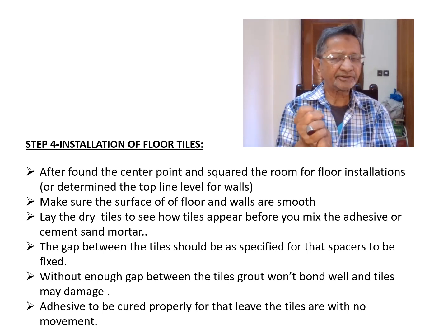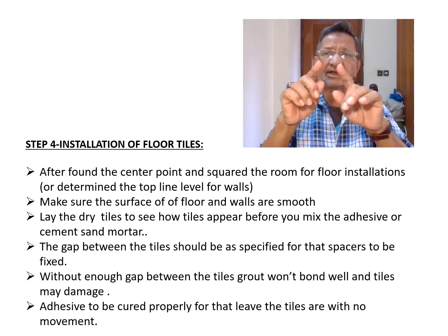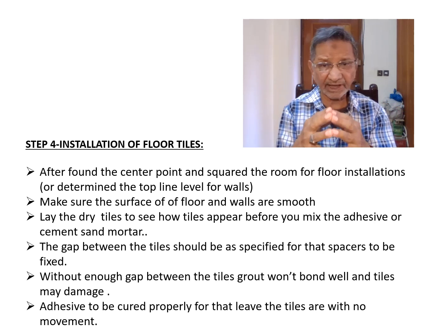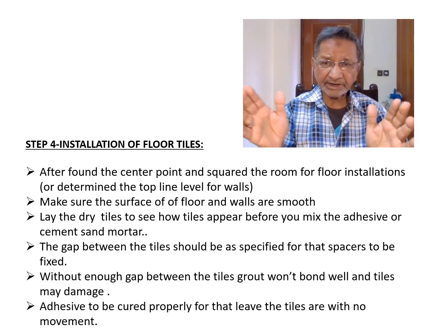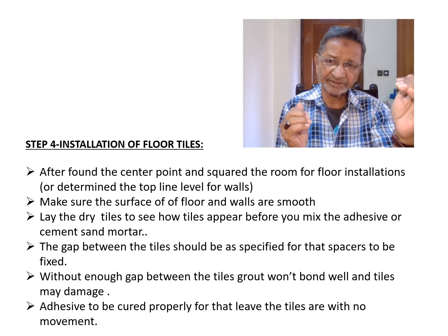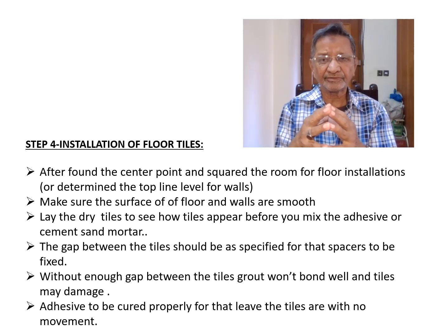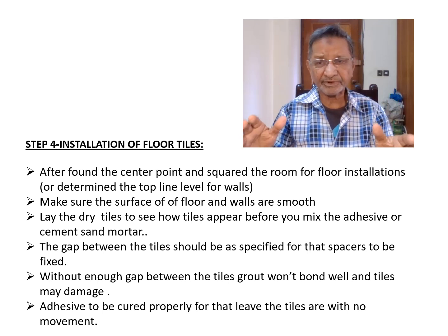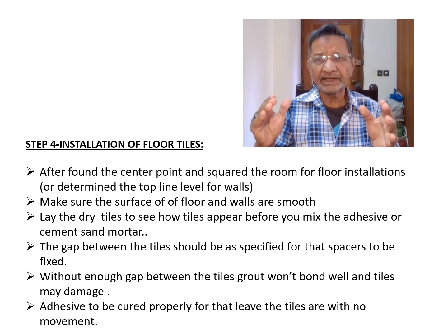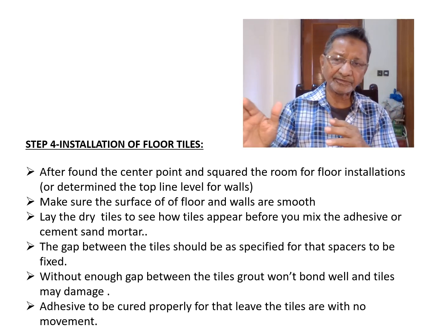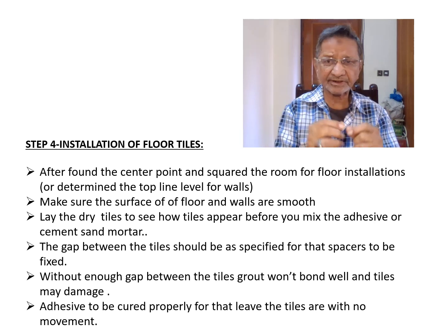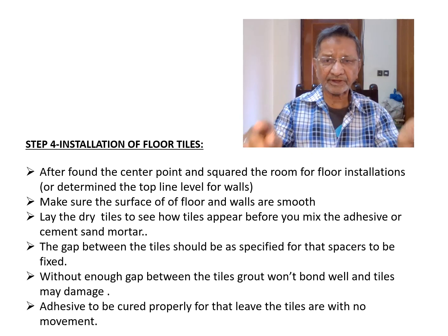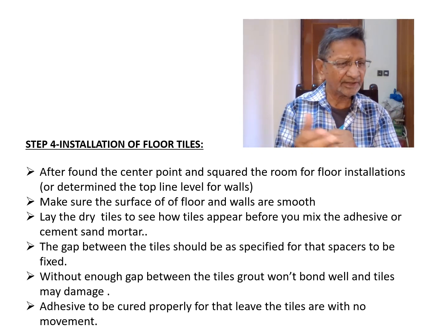The first step is that you have to mark the center and mark the square of the room where you are going to lay the tile, because if the room is a little bit unsquared, for example from one side it is 12 feet, and the other wall in front of that is a little bit less, even by centimeters, you have to mark the square of that room.